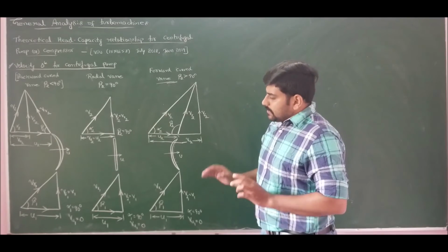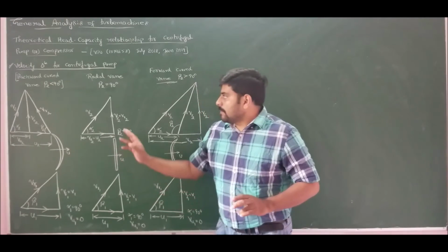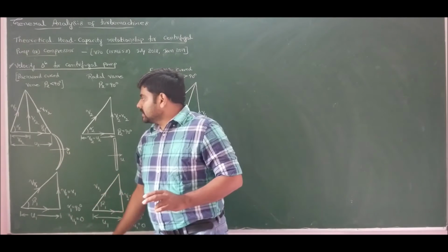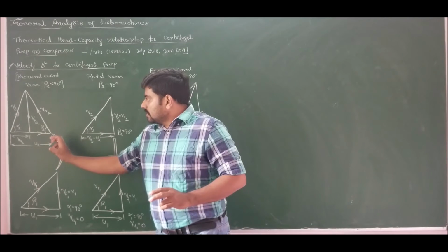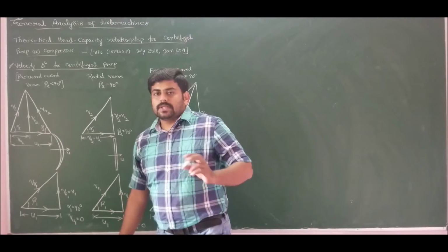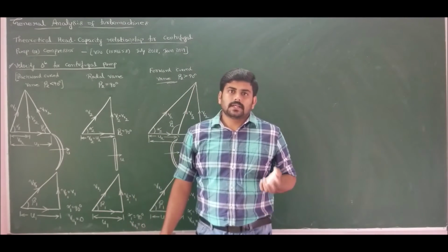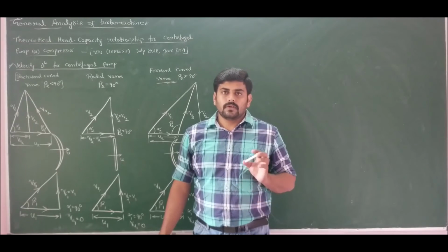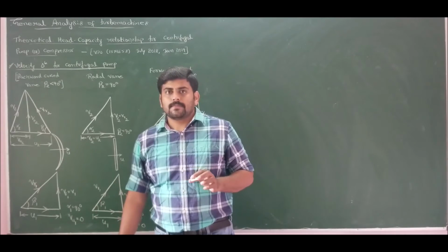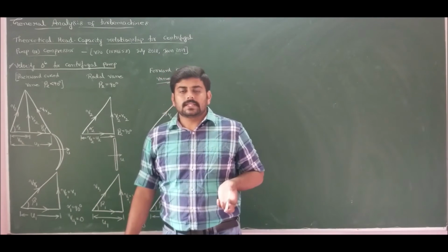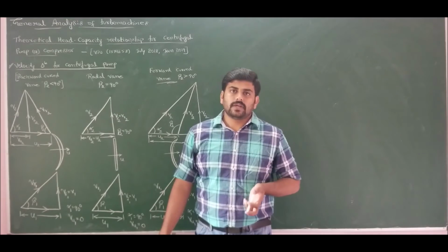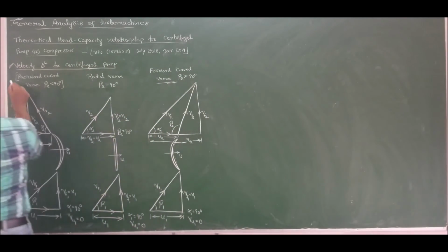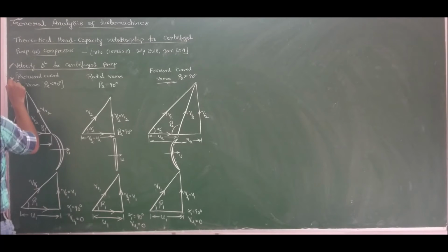With this knowledge, we always consider backward curved vanes the default. Backward curved vanes are advantageous, and if you observe for backward curved vanes, once we derive, we come to know that as head decreases, the discharge keeps on increasing. Therefore, we always prefer backward curved vanes. By default, if nothing is stated regarding the vanes for centrifugal pump problems, you should always start with backward curved vanes. Mark it as important. This is the default velocity triangle for us.